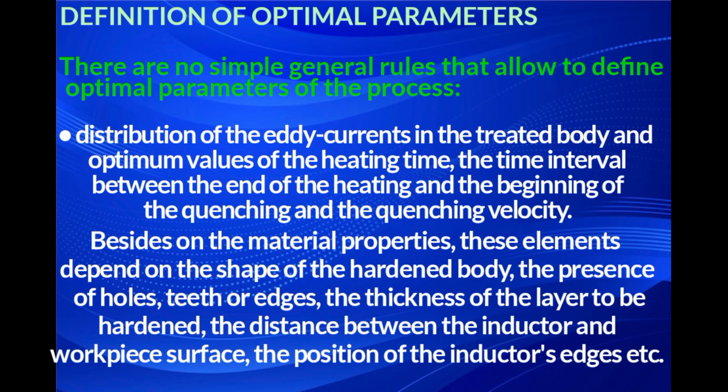Besides the material properties, these elements depend on the shape of the hardened body, the presence of holes, teeth or edges, the thickness of the layer to be hardened, the distance between the inductor and the workpiece surface, the position of the inductor edges, etc.